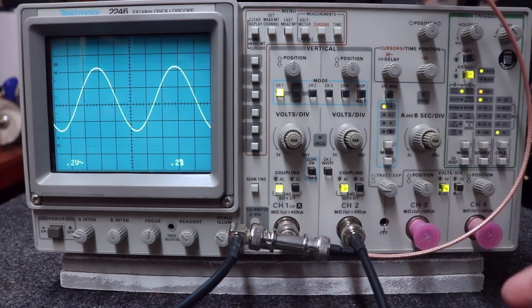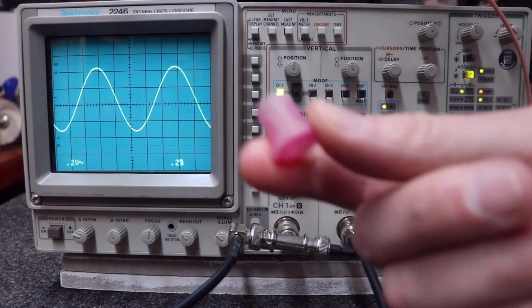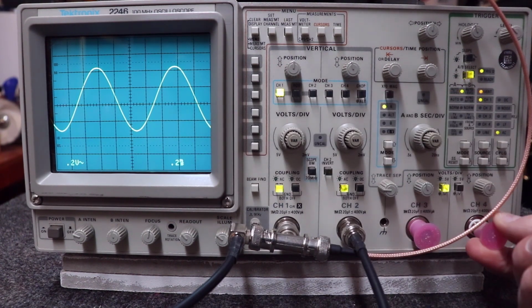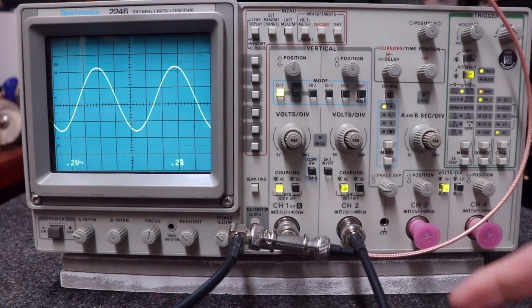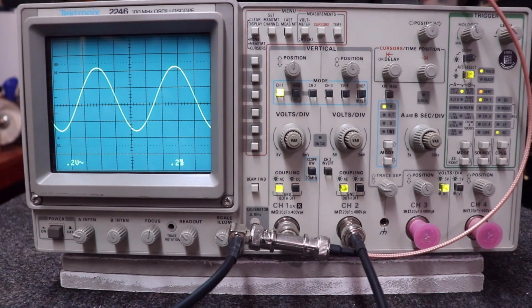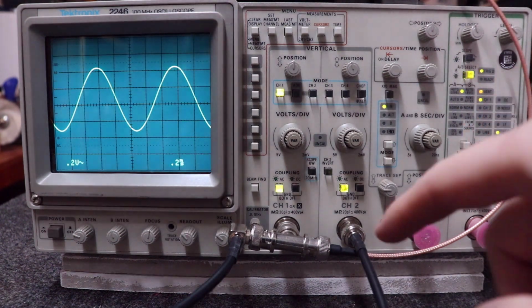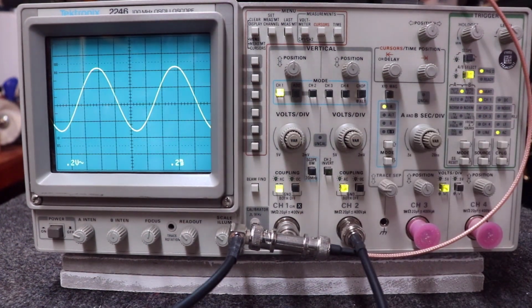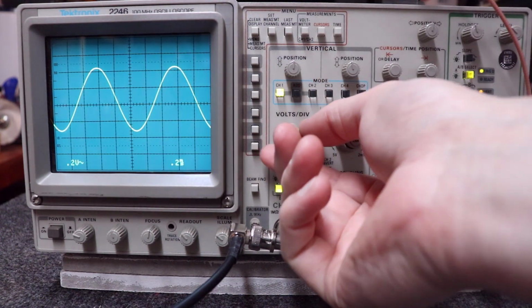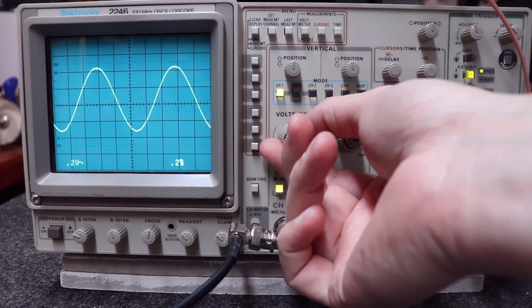By the way, this is a 4-channel oscilloscope. I keep these that I don't use often kind of covered up, and you'll notice there's dust on top of that. What that tells you is I do a lot of audio work and I only use 2 channels. So if you're thinking you need a 4-channel oscilloscope to do audio work, probably not. It's a hint. A good 2-channel scope will do everything you need, okay? So with that, I've got this little knob here that I turn, and guess what?